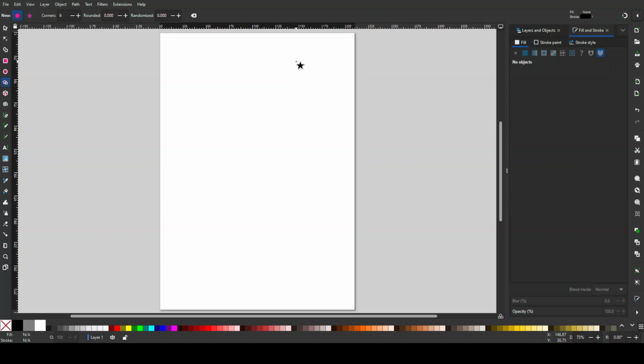So you would just go over to the left toolbar, and there are the tools where you can create a rectangle, ellipse, arcs, or circles, stars, polygons, and 3D spirals. It's really a lot more you can do with this. Adobe Illustrator is the paid version, which is even more powerful, but Inkscape to me is free, and I love free. So, and this allows you to create SVGs, which you can then import into Easel or other programs that you can use to control your CNC machine.